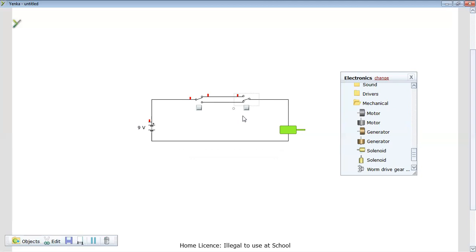Now, you'll notice that as it is currently not connected anywhere here, the solenoid is pointed outwards, the cylinder is shot out, it's not connected whatsoever. Now, as I switch any one of these switches, it doesn't matter which one it is, all I need to do is switch one switch, and that completes the circuit. And as you can see, the solenoid there, or the cylinder, has been activated, it's pulled in. I can click any switch, I can click the same switch again, and as you can see, it's turning it on and off.